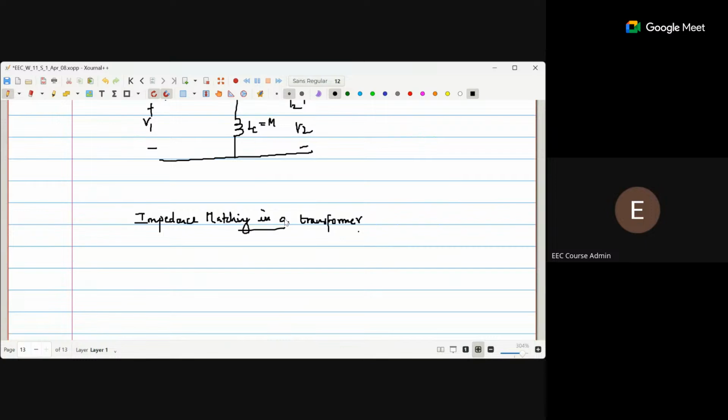So the fundamental idea behind this, you will be equating the power on both the sides, right? The power equations. So V1 I1 equal to V2 I2. What has been discussed first in the lecture for easy understanding is you connect a simple 1 ohm resistor in the secondary side. So you will have it like a load there.